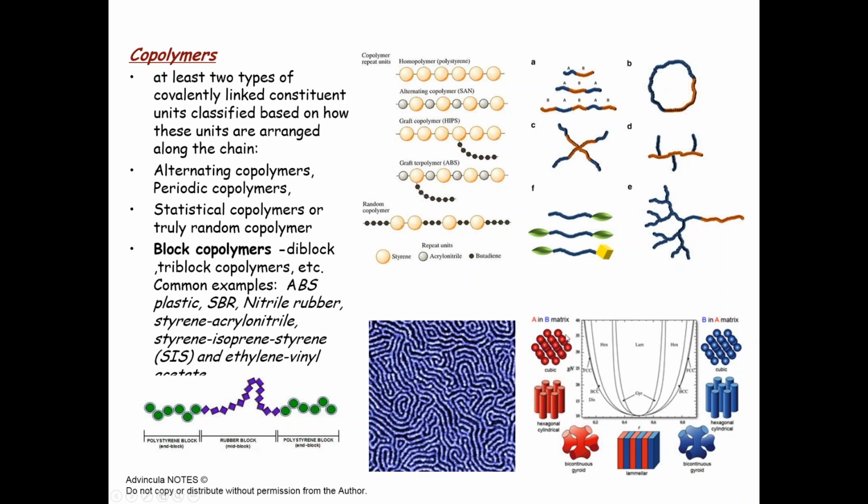So in this so-called Milner diagram, you see these different types of morphologies or phases predictable by the composition and the volume ratio, and in fact the chi interaction parameter between these two components, giving you these very interesting phases or morphologies. Now, block copolymer work is important, let's say, for production of rubber and thermoplastic elastomers.